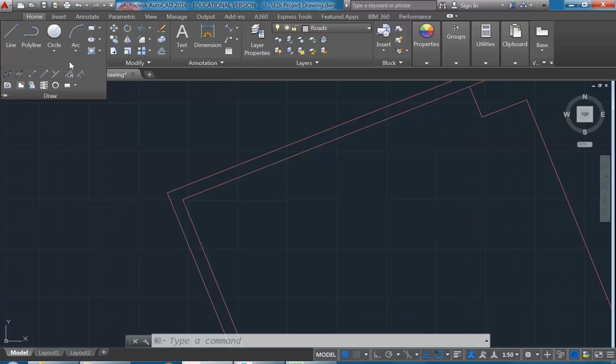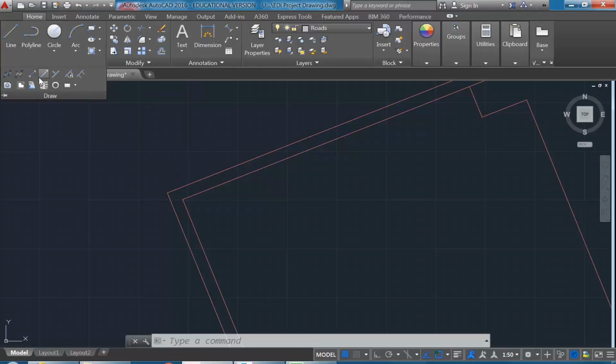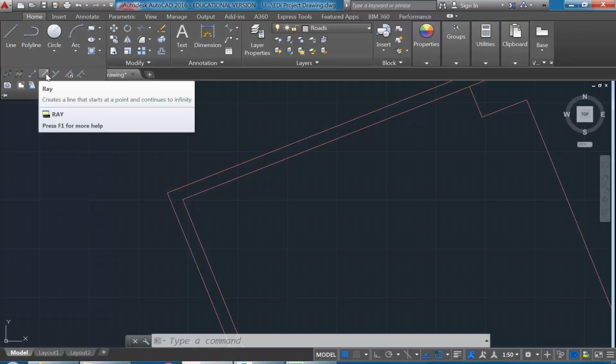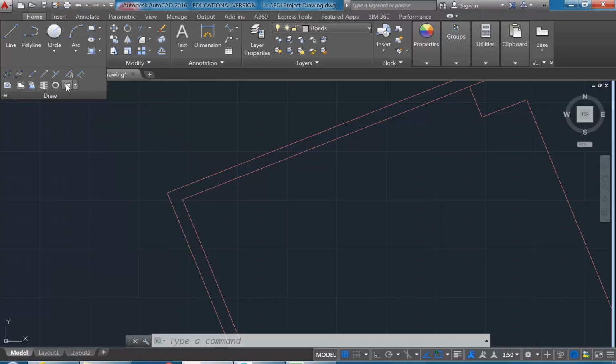And then I'm going to go under the Draw sub-menu there, and sorry, it's not there. Where's it gone? It's under one of these. So you've got there some of the options for points. Why can't I see the individual point option? Well, it's got multiple point there, which does the same thing. But actually, they used to have the individual point. I'm used to using the shortcut, so I don't look at these options all the time. But yeah, multiple point is fine. So this one here.